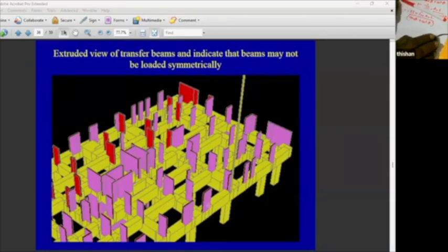What you can do is you can bring it out. The center line can be brought out, and then the transfer beams will be shown as a band projecting out of the building. That is one possibility. Then you might be able to bring most of the beams in line with the walls above. So that's one possibility, but not always, because sometimes in restricted sites you can't do that.